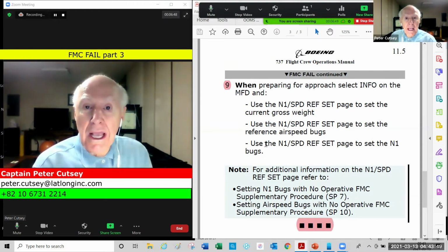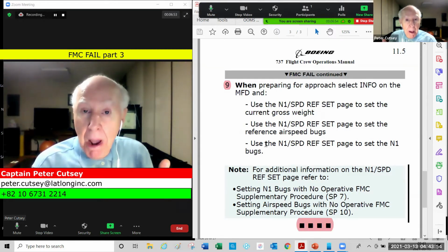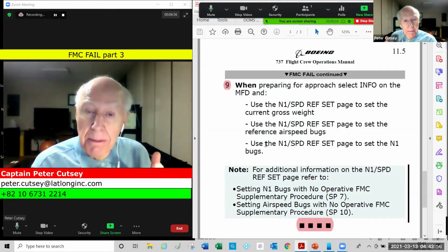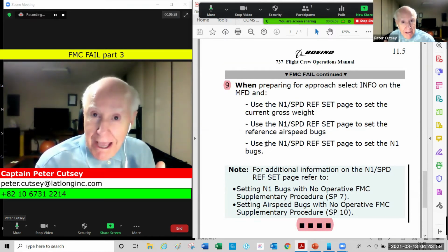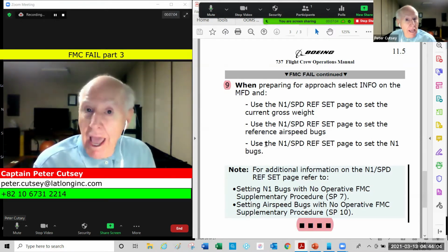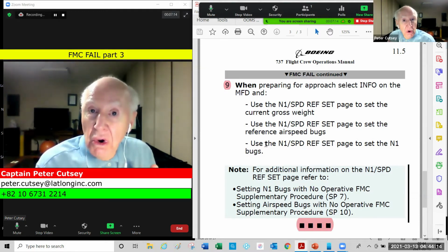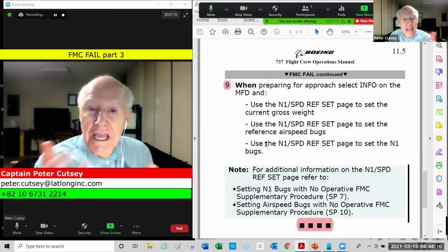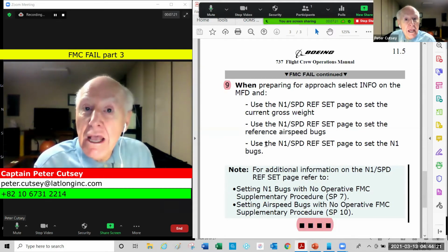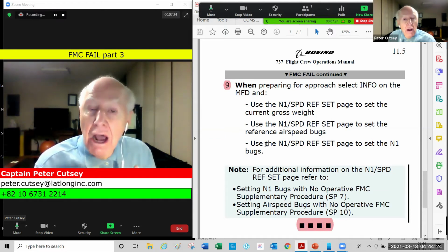You would do a quick DODAR. You diagnose what the problem was. Yes, we have diagnosed the problem. You have options. Yes, we either continue en route or we're going to stay. Our option today is that we can't go en route in an RNAV environment, so we're staying over Muscat using conventional navigation. And that's what your decision is in the DODAR. And your actions, you're taking your actions now, you're doing the checklist, and then you're going to prepare for an approach and landing here at Muscat and a review.